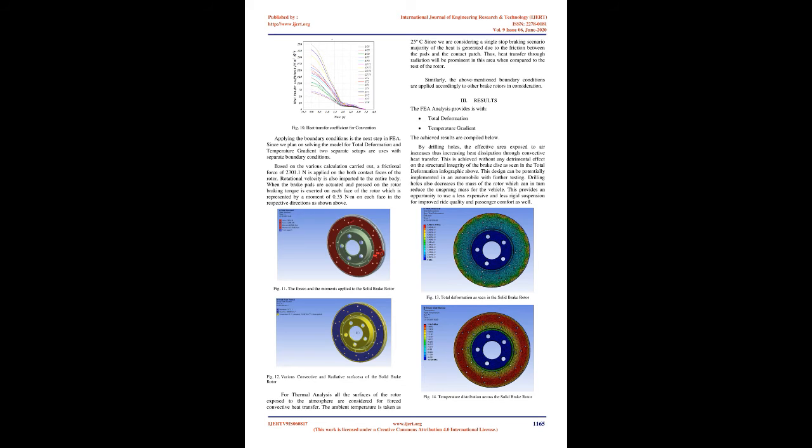Braking torque on disc equals 354.42 Nm. Clamping force equals 2301.42 N. Heat flux equals 48.58 kW/m². Convection heat transfer coefficient equals 250 W/m²°C.